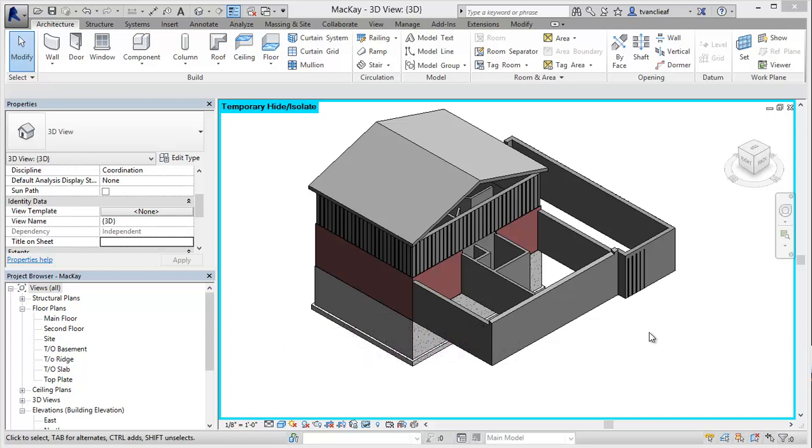And for our next video in this Revit series, I wanted to take a look at some more complex stuff with creating walls. And it comes at a pretty appropriate time because a friend of mine recently asked me how you might create a board and batten wall type in Revit. And I think the best manner to do that is to do it in a two-step process. So create a wall type that's similar to your board and batten, save for the strips that go on the outside, and then create those as a sweep after the fact. So let's take a look at this process.